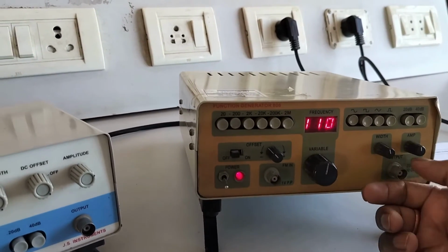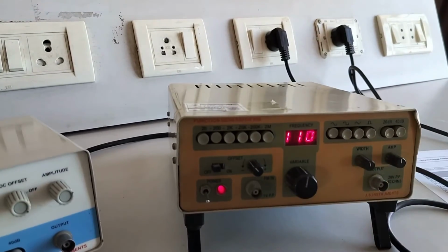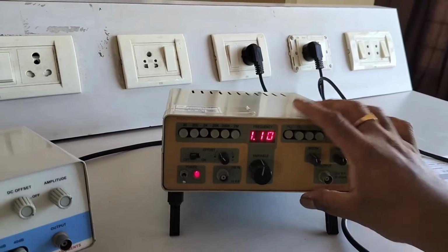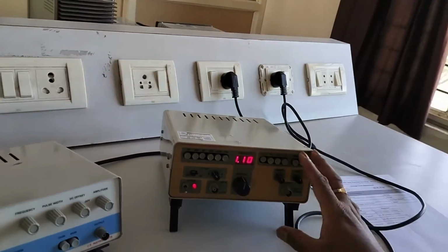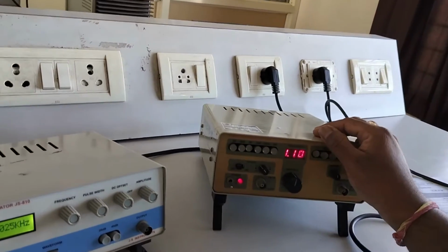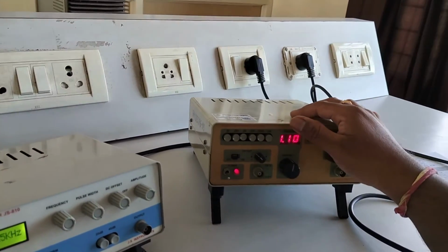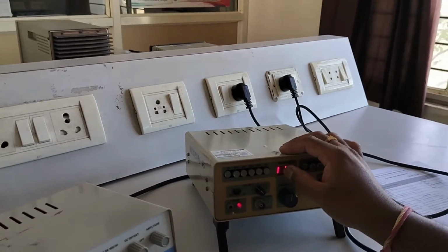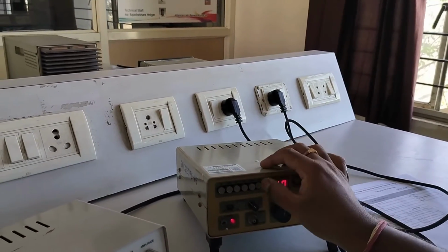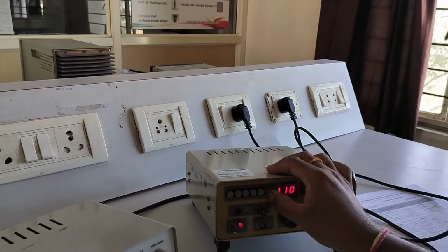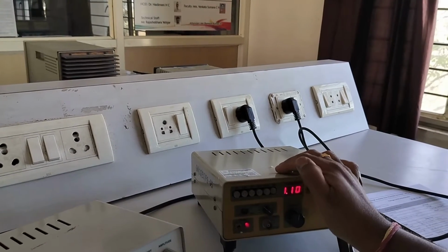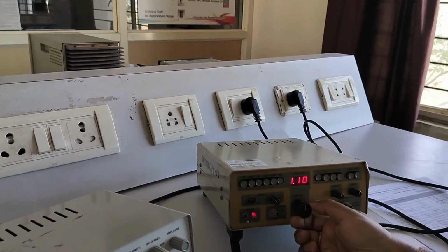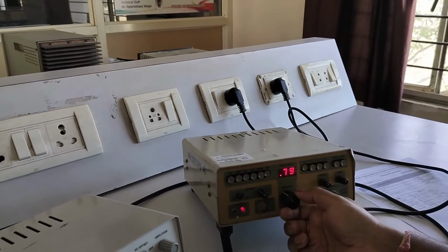The main thing is we are taking the output from here, the function generator. Since it is a source device, it is giving certain voltages and frequency. Usually we say audio frequency oscillator also, that's another name for function generator. An audio frequency oscillator means audio frequency is 20 hertz to 20 kilohertz. But now the function generator has come because the maximum frequency available is 2 mega, and 10 mega also is available. And this is the variable knob to adjust the frequency.